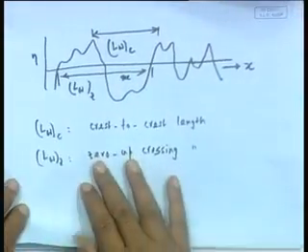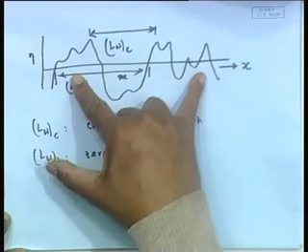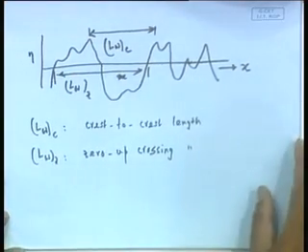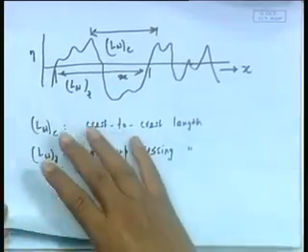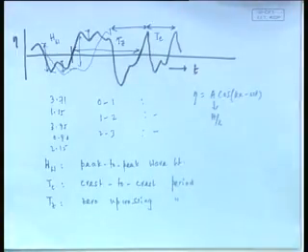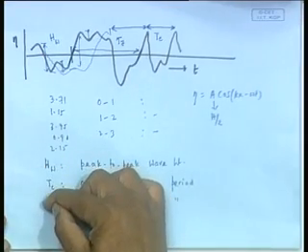Normally, of course, we do not collect this data, because remember, collecting this data requires you to take a snapshot over a distance, which is not done. Typically, you have a data buoy located at some point, collecting data at that location against time. And of course we know that theoretically length and period are connected to each other through the dispersion relation. So in practice period is collected, not the length.